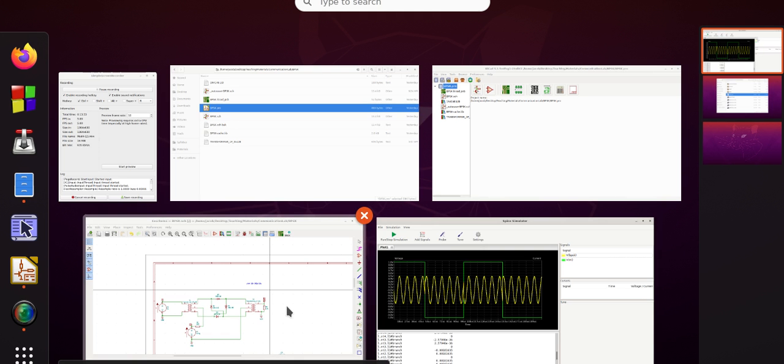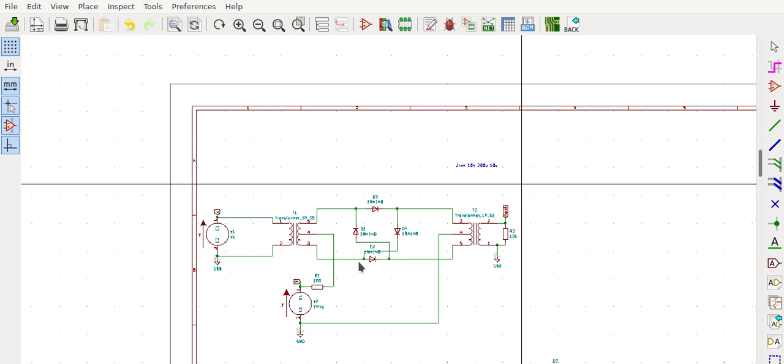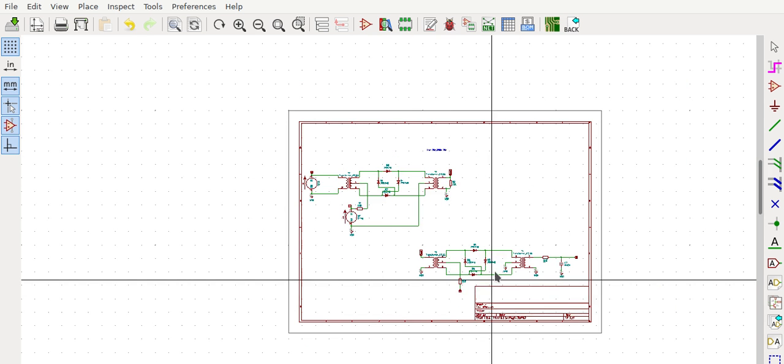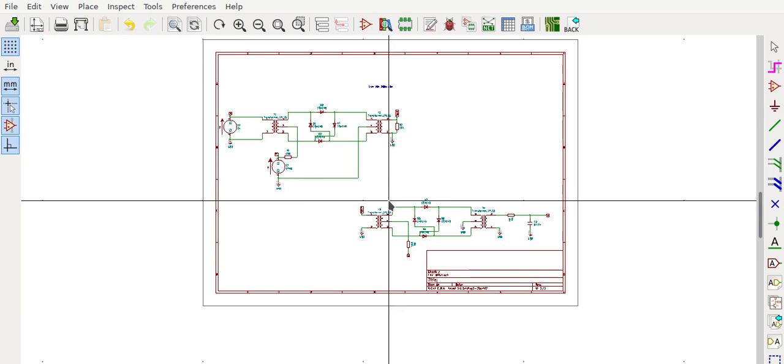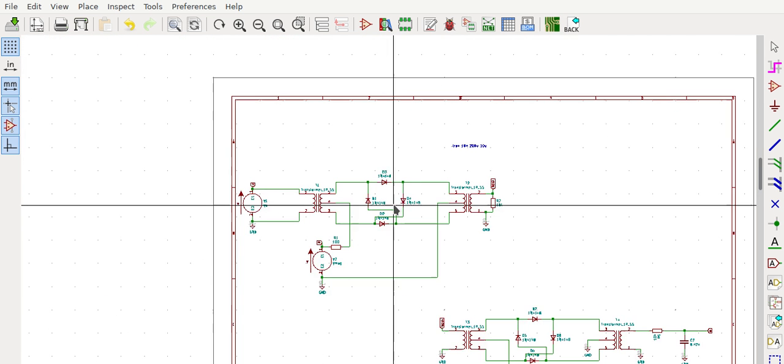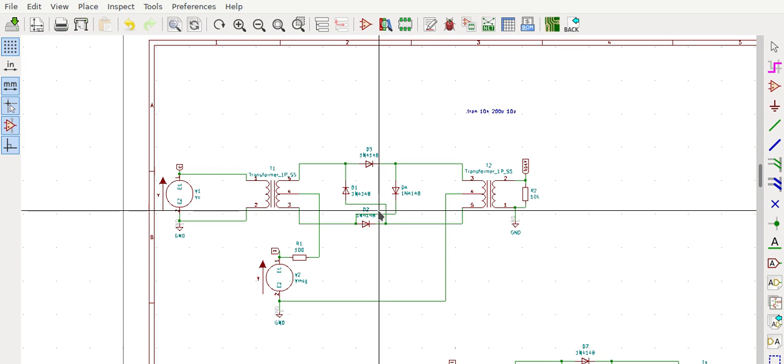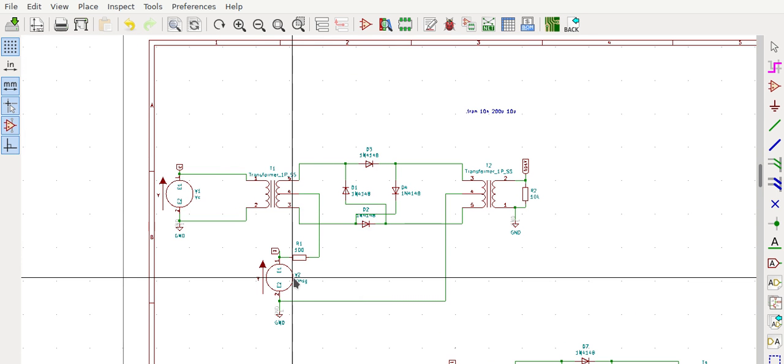Okay, so let's come back to the circuit, and let us see how the demodulator is set up. So I have said that the other way to look at this circuit is as a multiplier. So when the message signal is 1 volt, you are multiplying this sine wave with 1, and when it is -1, you are multiplying it with -1.